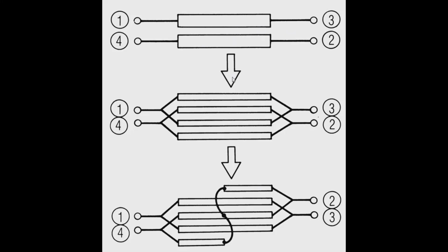I should also have mentioned an interesting characteristic of this coupled line directional coupler. The phase difference between port 4 and port 3, for all couplings by the way, is always 90 degrees. And it's 90 degrees from DC to light, not just at the center frequency. It's an interesting property.